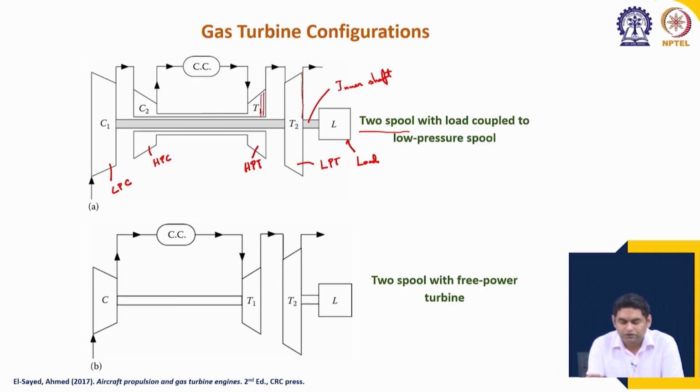On the other hand, the inner shaft which has the low pressure turbine and compressor can be rotated at a lower speed such that the centrifugal stresses do not exceed the material limit and there is no problem with the continuous running of this type of turbine.